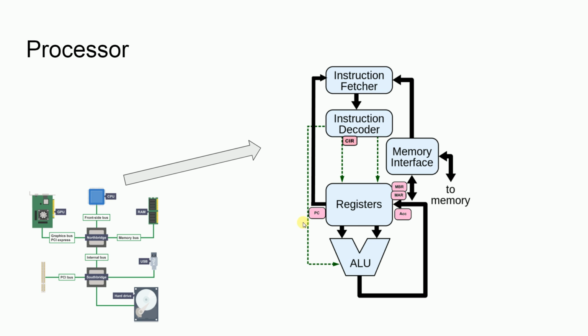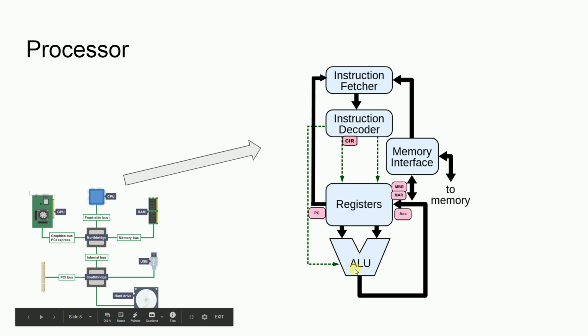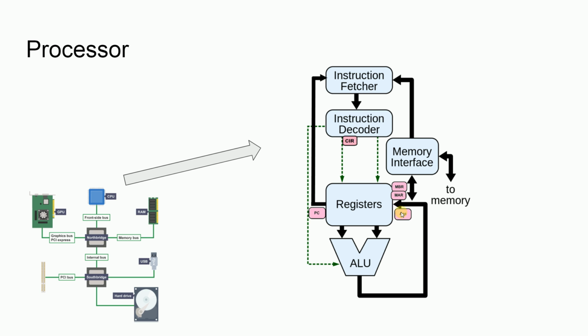So the instruction decoder then chooses what operations need to happen. Are we doing a store? Are we doing an add, a subtract? Are we doing a check? And it uses those circuits to perform a calculation. And the result of that calculation is often returned in what's called the accumulator, or associated with that, it can change a series of status registers, which hasn't been put on this diagram.